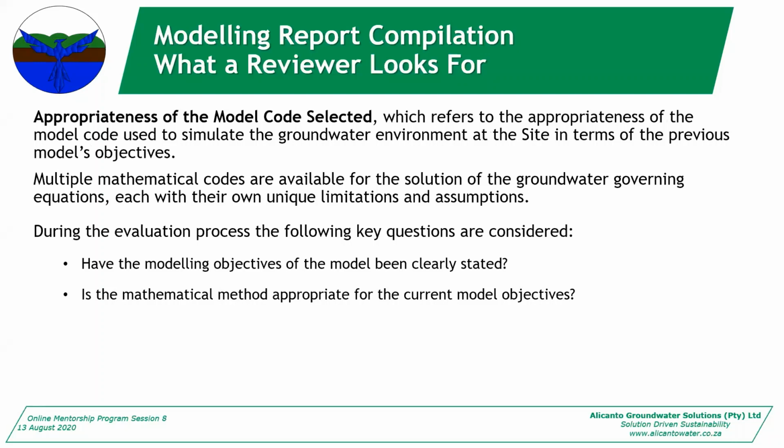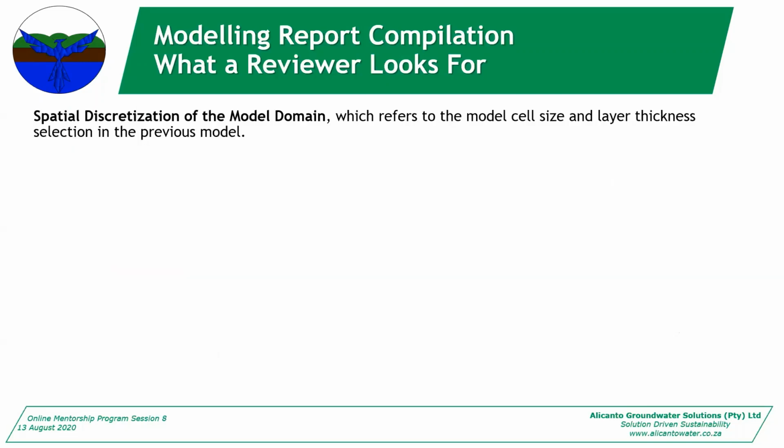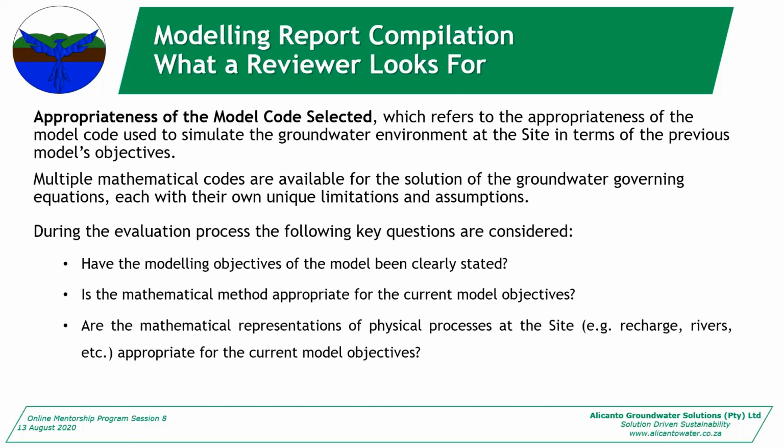The assumption of the model rules it out. And are the mathematical representations of physical processes at the site, such as your recharge, your rivers, drains for your mining operations, all those kinds of things, appropriate for the current model objectives? Does your model represent the site properly in terms of what you're trying to achieve?